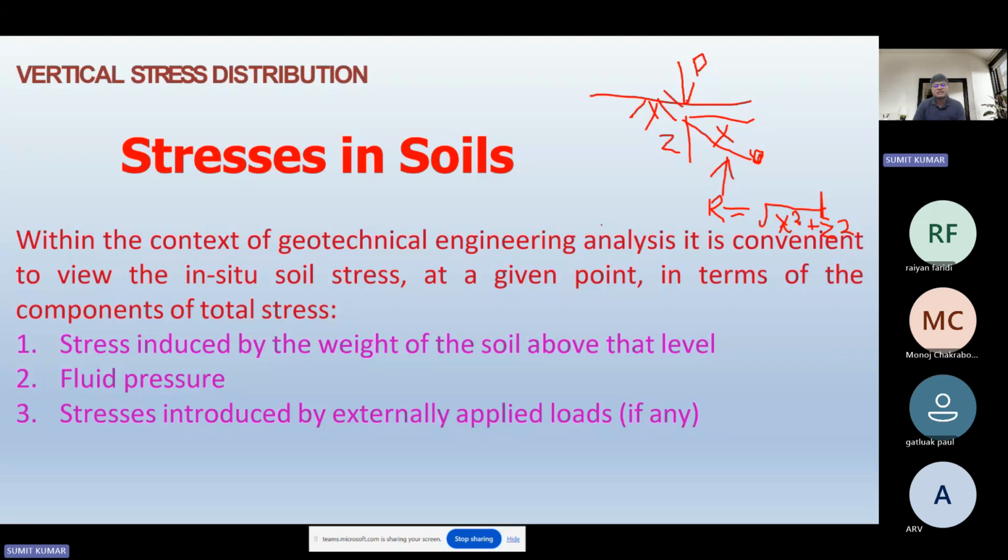But once it was seen that many of the structures got damaged, the term effective stress came into the picture, in which we consider that if pore water pressure is there, it will result in a decrease in the effective stress value. Hence, in association with that, the effective stress approach gives a better picture of the stress distribution through the soil. So, in general, in the earlier times we calculated the stresses in soil in terms of total stress only.